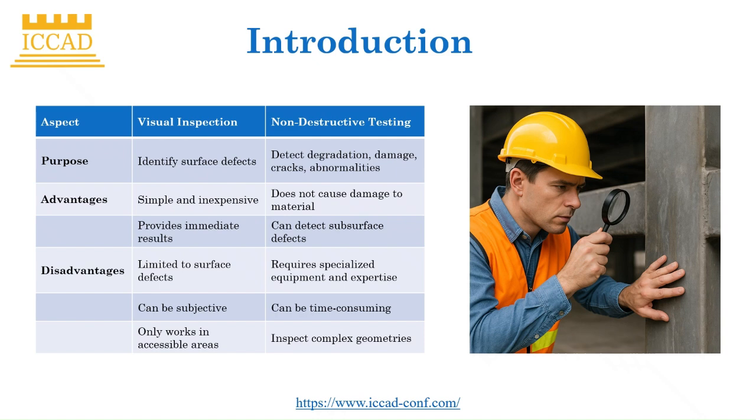On the other hand, non-destructive testing detects degradation, damage, cracks, and abnormalities. It does not cause damage to the material, and it can detect subsurface defects. It requires specialized equipment and expertise. It can be time-consuming, and it's limited when it comes to inspecting complex geometries.